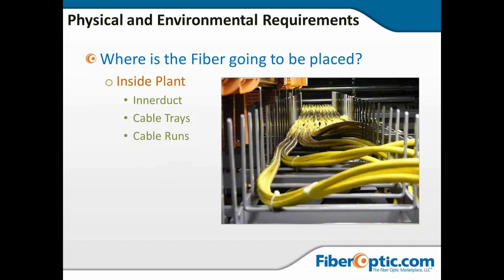Now, in the inside plant, are we going to use interduct, cable trays, cable runs, ladder racks? What kind of tray are we going to use? If we use duct, we've got to look out for fill ratios. If we use cable trays, such as the one that's shown here in the picture, we have to consider how much fiber can we put in it, how many fibers are we going to add to it later, how much are we going to need to change it?